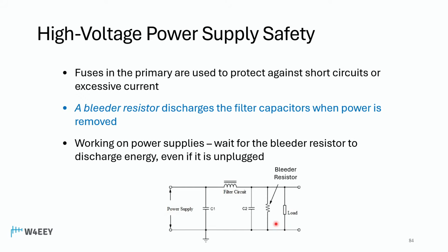And its purpose in life is it doesn't take a lot of current because you want most of the current to go to your load, but it's drawing enough current so it will discharge this capacitor over time. It might take half an hour for it to get down to 0, but it's a huge safety item. Most people that work on these power supplies will always short out those output capacitors before they get in there and start poking around because we're talking lethal voltages here.